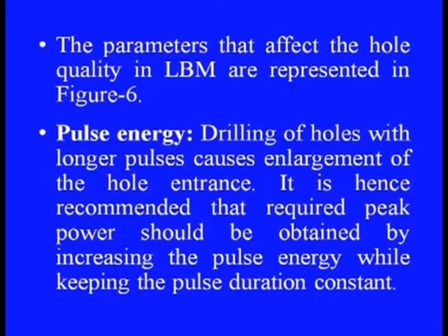The parameters that affect the hole quality in laser beam machining are represented in the following figure, in which pulse energy is one of the important parameters. Drilling holes with longer pulses causes enlargement of the hole entrance. It is hence recommended that the required peak power should be obtained by increasing the pulse energy while keeping the pulse duration constant. This is schematically shown here.